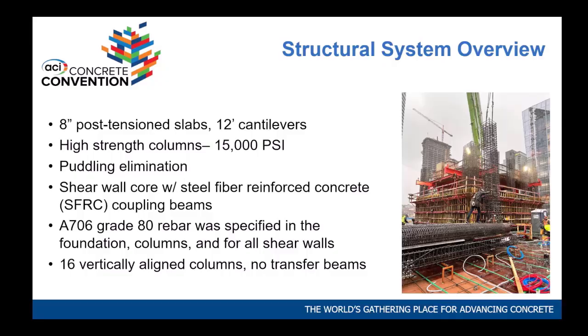It takes a lot of energy. You put in 11 pairs of ground motion. Each one is about a minute long, and every 0.05 seconds, you check the stresses on the building as the 11 pairs move that model. So it takes a lot of iteration, a lot of back and forth.